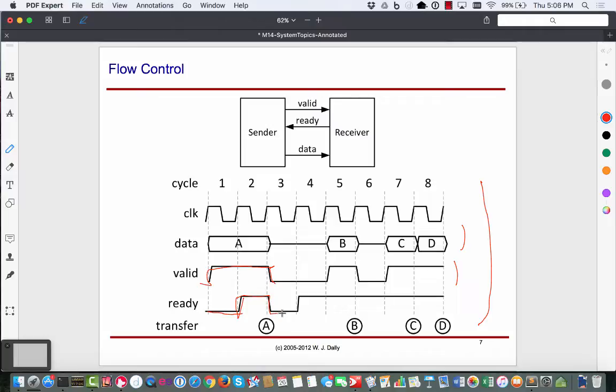You might read about terms like 2-phase handshake, 4-phase handshake, things like that. But common to all of them is that the sender says, hey, I'm ready, somehow the receiver says, hey, I'm ready or I'm done, and then the two parties exchange data and move on. Now this ready and done part in buses which are on the chip or on the board are separate lines. There would be pieces of wire or pins. But on things like USB, these are bits embedded in the same serial data stream.